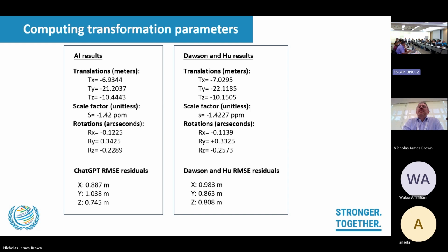So what if the residuals are very high, and the suspicion would be on the quality of the ellipsoidal height, because in the old system we were trying to make the ellipsoidal height 0 instead of throwing them away. I'm not sure that is a good strategy. Of course, when we do that, the residuals become very good because the height, the third dimension, actually impacts the computation.